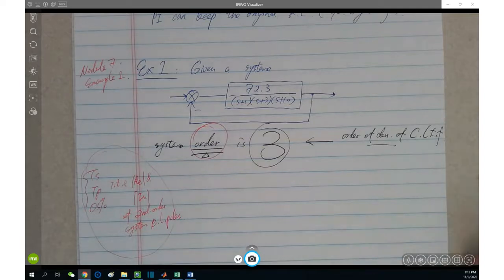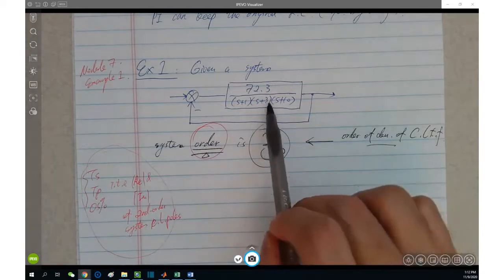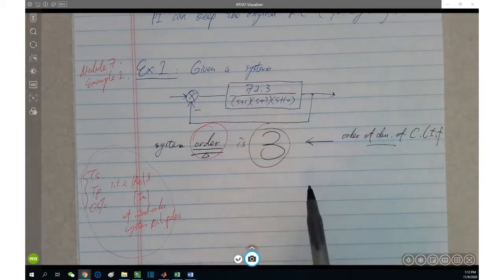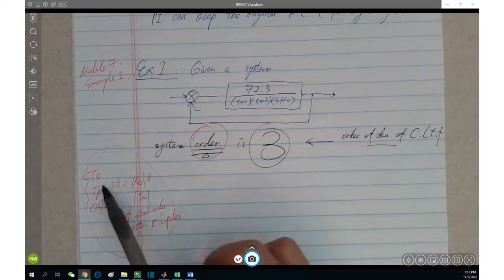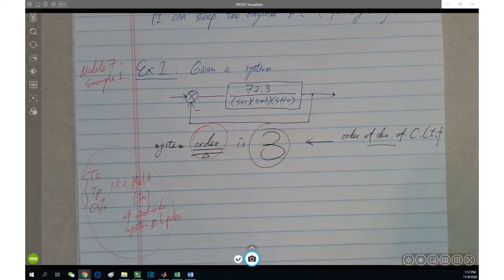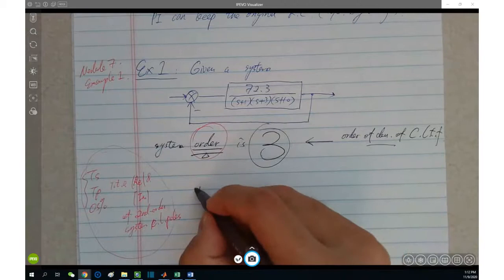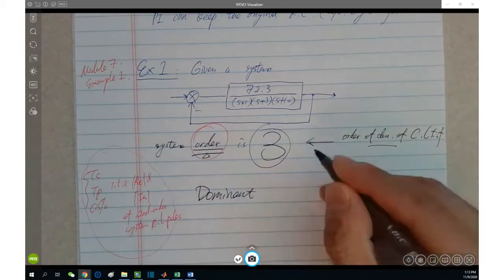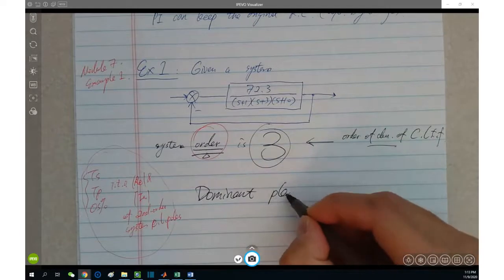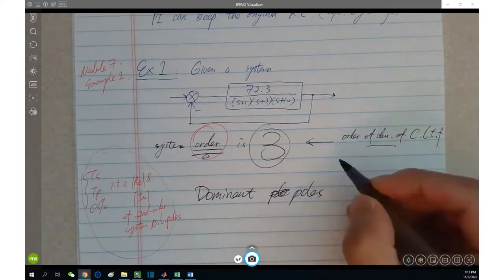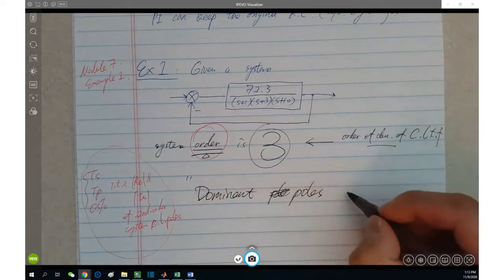So here I need to clarify now before we go further, because this given system obviously is not a second order system anymore. And the final project given system is not a second order system either. However, we're going to keep using these second order system conclusions here. The reason is here, and this is called the dominant pole rule.